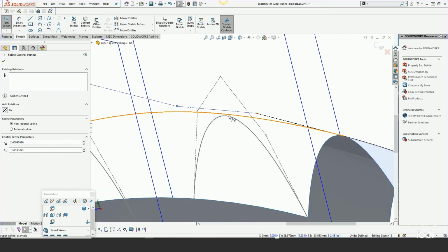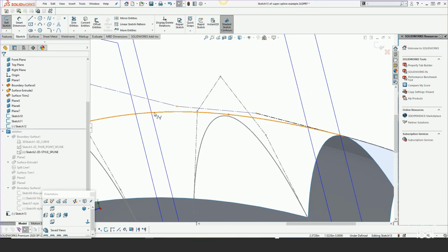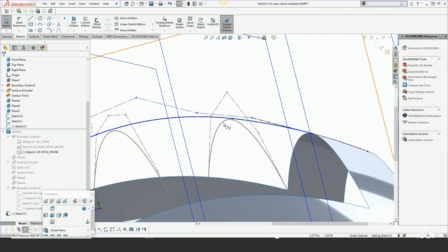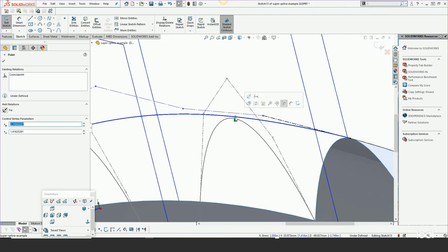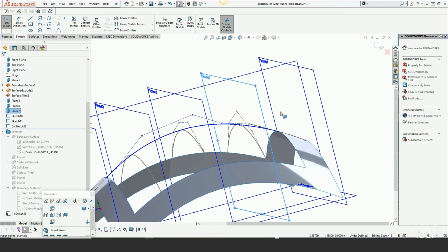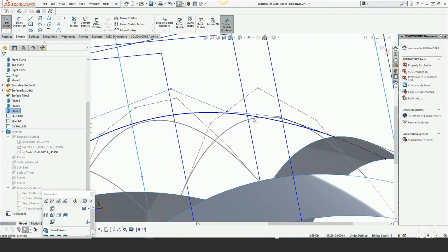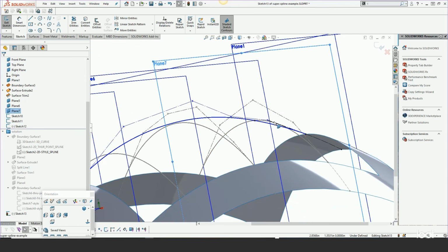And what I mean by that is I'm just going to use a sketch point and constrain it to the style spline. And I'm going to do that individually for each one of these that pierces through. So with that, I can take that and control select this and make a pierce. And what it's doing now is it's taking the style spline and all its advantages, but it's constraining it to those existing splines.